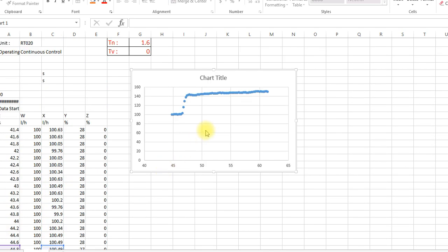So how to explain this? Is there any overshoot? No, because it is not going beyond the set point. It is reaching here and then almost coming back, and then again reaching the set point almost now here. So you can say that this is taking too much time, or it has sluggish response or slower response.